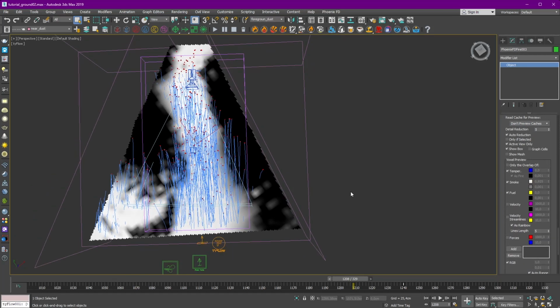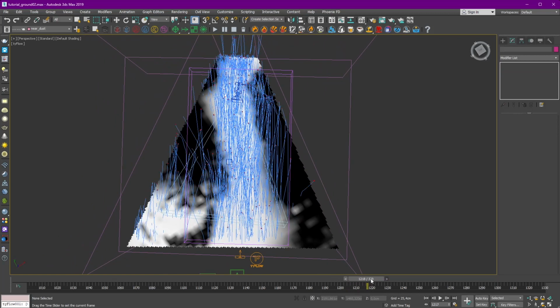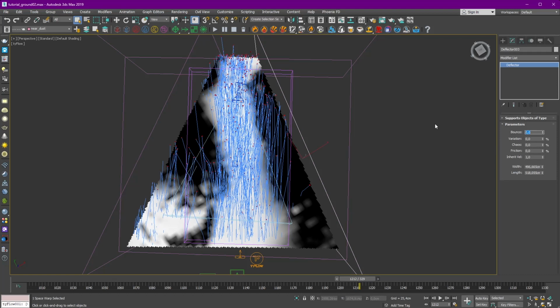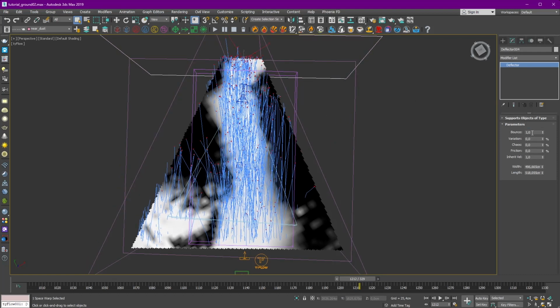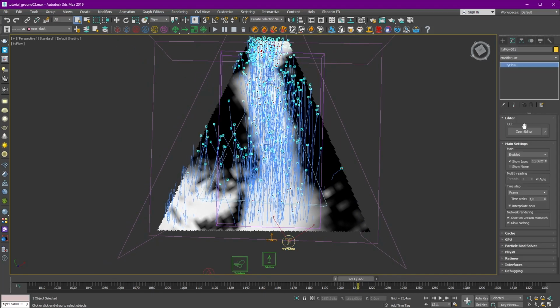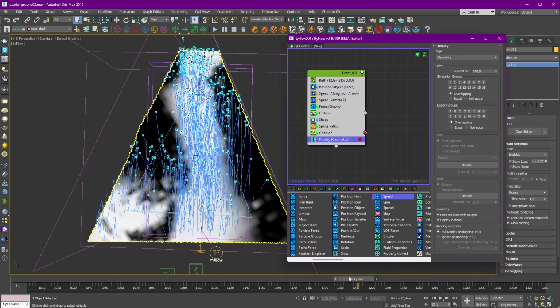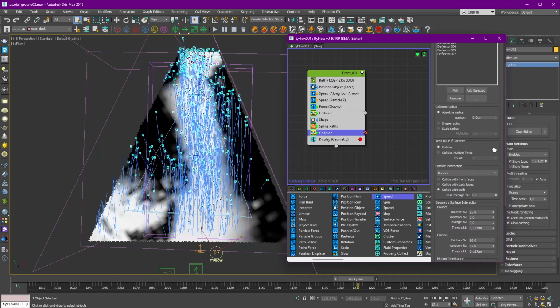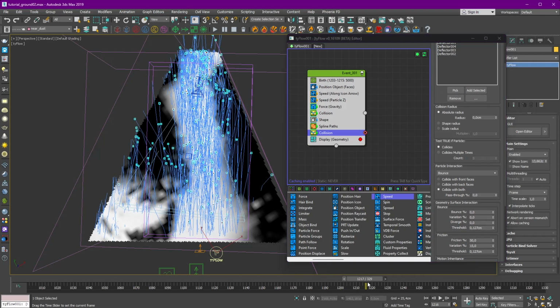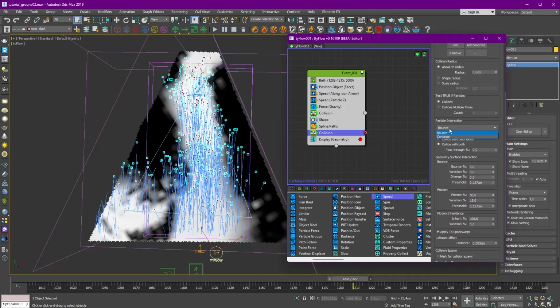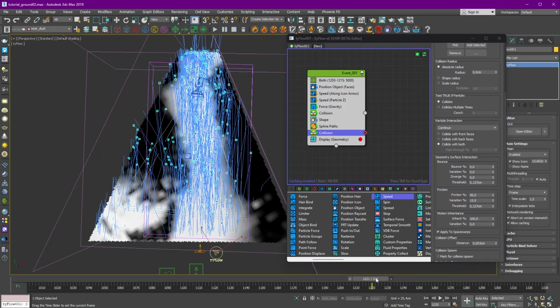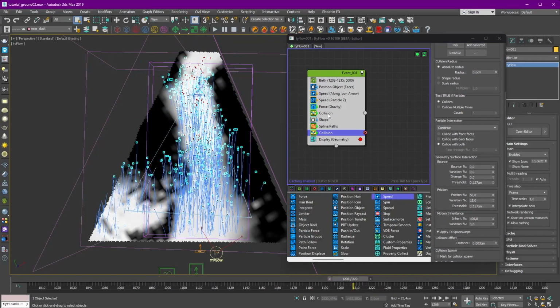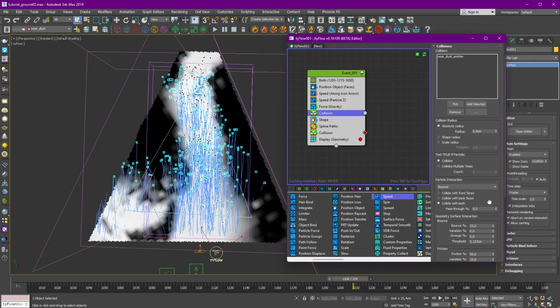Okay, and let's hide our simulation. Okay, now we emit our rocks only from the sand area of our ground. Let's bring bounce to 0 from our deflectors, because we don't want to bounce particles from there. Okay, it's weird because I can see that the particles are still bouncing. Let's bring bounce 0 also to this operator. Change to continue, but still on the right side next to the camera, I obviously can see the bouncing.